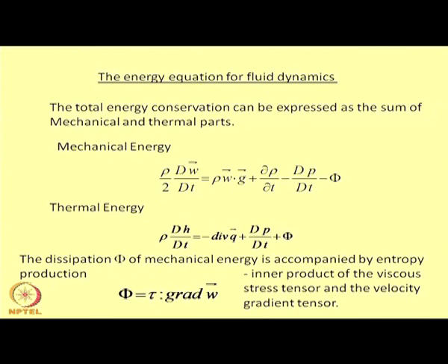It can also be termed as the amount of dissipation that would result because of fluid friction, and this fluid friction increases entropy. In some textbooks, phi is also referred to as the entropy generation. The larger the value of phi, the larger would be the pressure drop, the larger the temperature rise, and the larger the frictional force opposing the flow in such systems. So this entropy generation has to be kept to a minimum in order to build an efficient system.